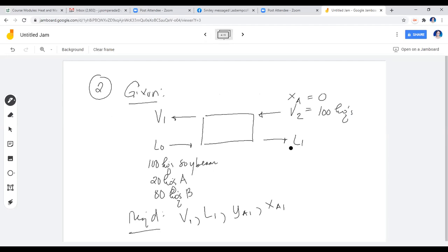If I may ask, since the problem is saying... I'd like to read that part. I missed reading that. The value of n for the slurry underflow is essentially constant at 1.5 insoluble solid over kilogram of solution. What does this mean? This means that your n in this problem is constant with a value of 1.5 kilograms. That's the N in the slurry. So that would be 1.5 kilograms B over kilograms of solution.